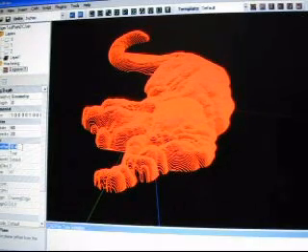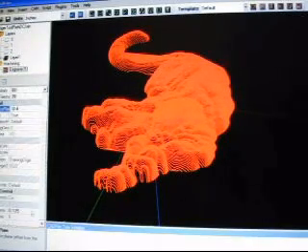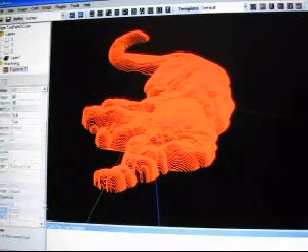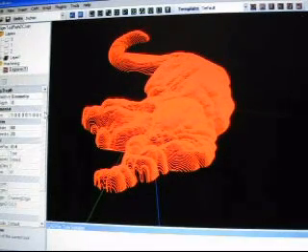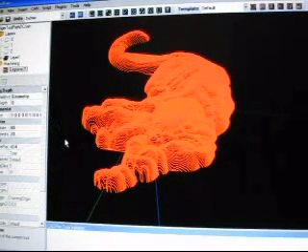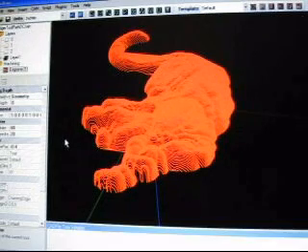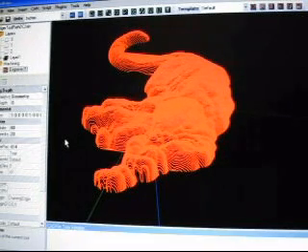Like I said, the tool diameter doesn't matter. It only matters when you want to verify it in Camotics. Then it's going to make a little bit of a difference there, but we can adjust that as well. That's not a big deal. It's just a T2 or T3 or T1, 2, 3, whatever you want, and then an M6, to tell the machine to do what you want it to do.